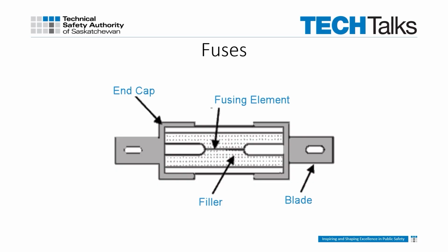In general, fuses are a fusible link or element encased in a tube or housing and connected to terminals. The link has a resistance that is very low and acts as a conductor until it encounters current levels that exceed its amp rating. When the rating is exceeded, the link melts and opens the circuit to protect conductors, components, and loads connected to the power through the fuse.